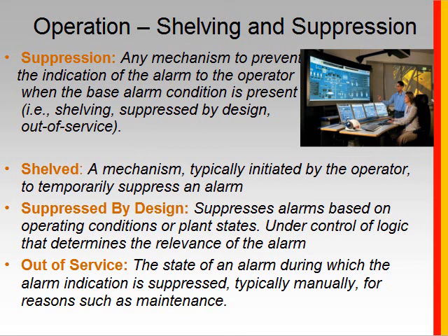And the standard defines 3 different types of suppression. The first is called shelving, and this is a functionality that is typically presented to the operator to use. In this case, the operator is allowed to take alarms that are created or show up on his screen and shelve them, which means temporarily remove them from their view.